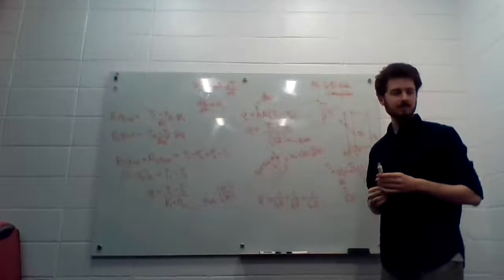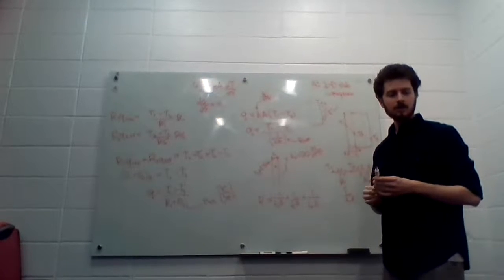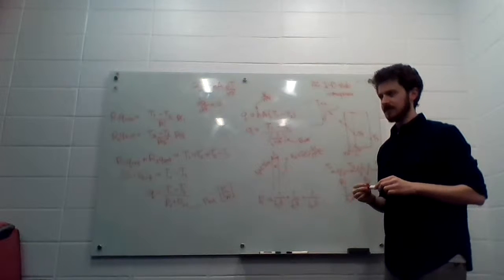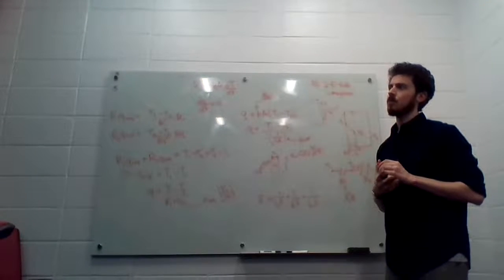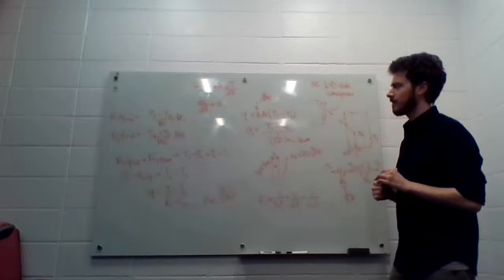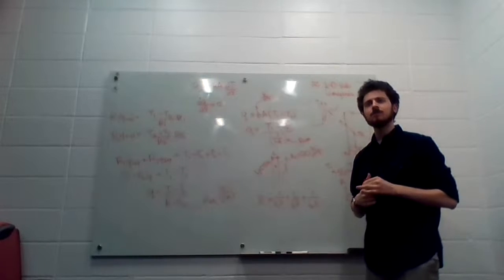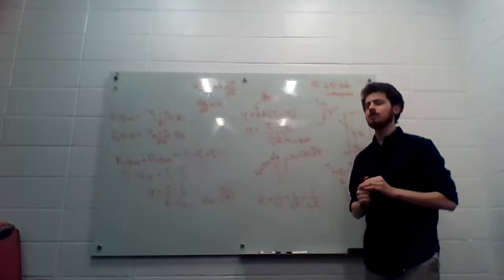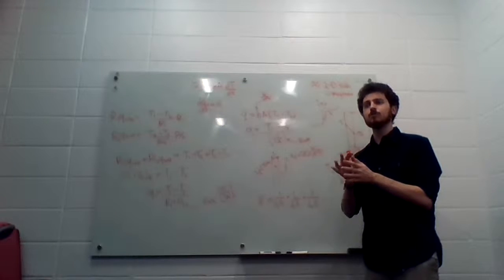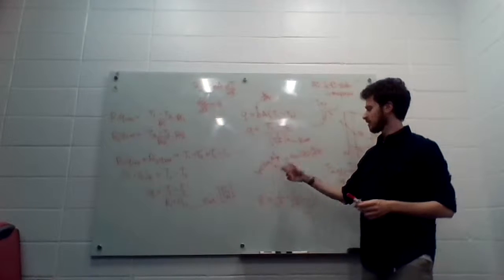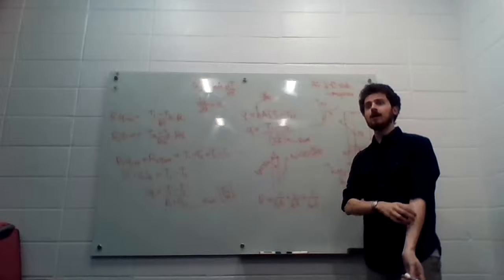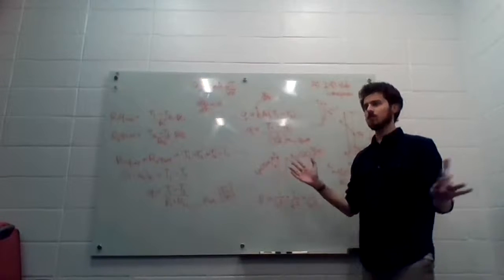I think that's everything we have time for today. The one other thing I wanted to play around with, and maybe I'll put a problem on the next homework about this, is that when you're dealing with thermal circuits, you end up with big changes in magnitude. So if you had just a simple aluminum panel as your wall, you really can't neglect the resistances created by your convection coefficients. And if you did, you'd get totally wrong answers.